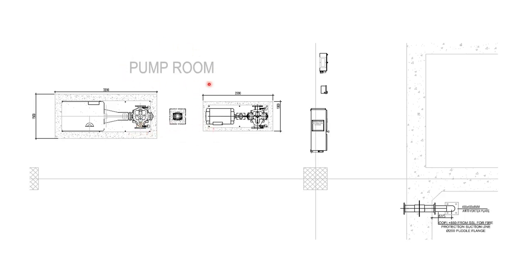And next we need to propose the foundations based on the actual dimensions of the fire pumps. These dimensions of the fire pumps have to be taken from the manufacturer. So this is the most important point to be considered. Apart from that, these foundation details are necessary, and these details have to be given to the civil contractor so that they will start working at site.